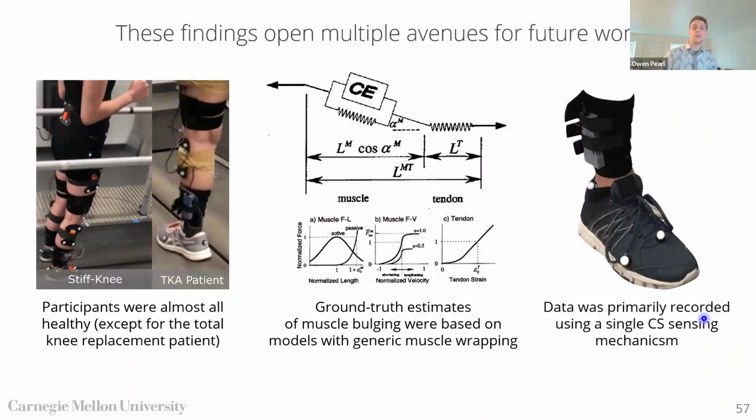And third, almost all this data was recorded using a self-capacitance electronics architecture. There's actually a lot of different electronics architectures behind capacitive sensing, and they should in theory be similar, but there's more testing to be done to see how different electronics architectures would change the resolution or the sensitivity of the measurements on gait data specifically. So there's more room here from a mechatronics perspective on how to design these sensors. Together, this finishes the muscle activity with capacitive sensing project that I talked about.